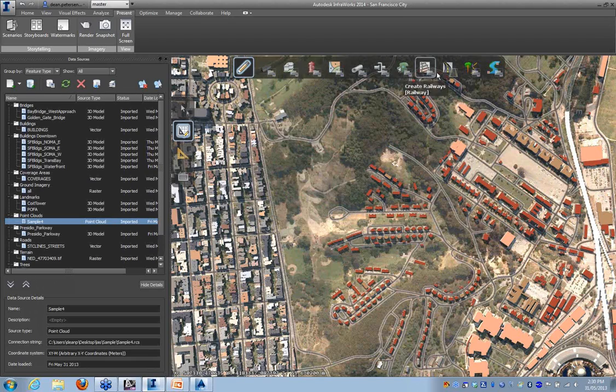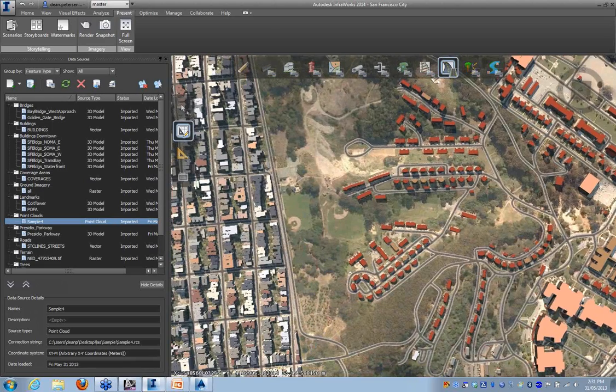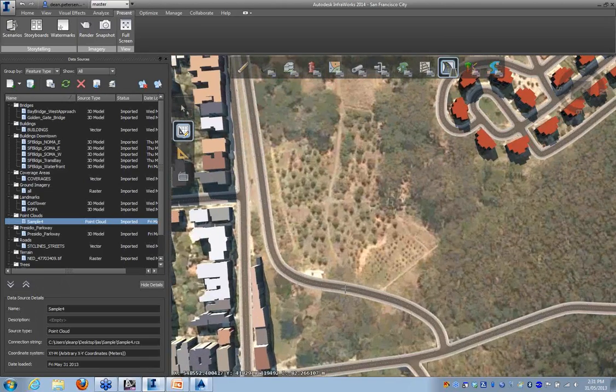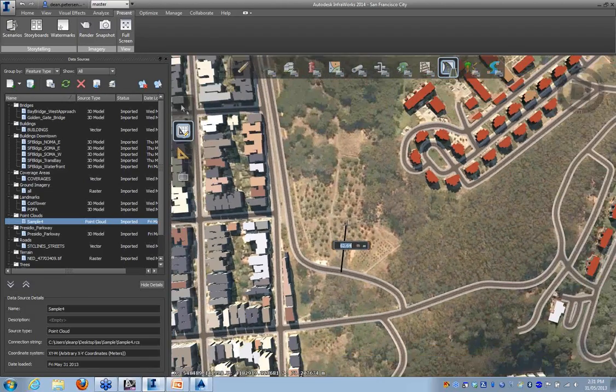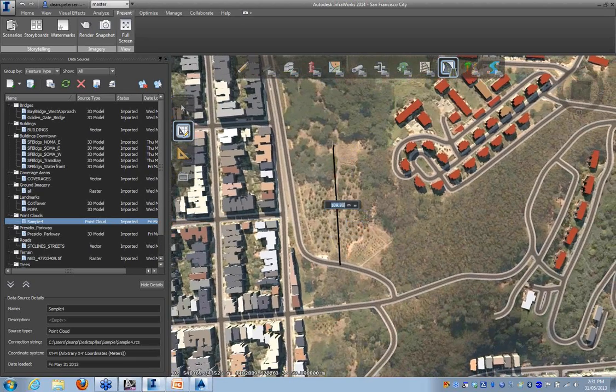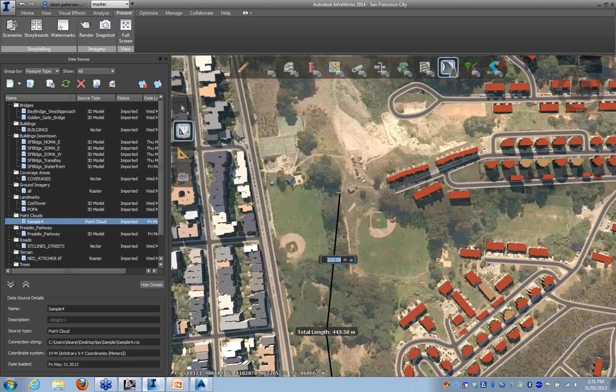So you can draft in roads normally, but this allows you to do a little more in that you can, let's design a collector road, shall we say, and I'm going to attach it to there, and this is all normal, what you would do in the previous version of the software. But you can see as I draft it in, I'm starting to get curves and tangents being placed in. So this little orange curve appearing down the bottom of the screen, there's another curve in here.